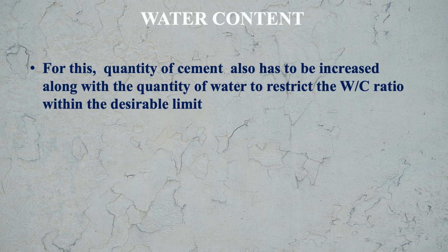Means if we have to at all increase the water content, then we can do one thing, that we can keep the water cement ratio constant, means within the certain limit. And how we can keep this water cement ratio within the limit? Means if you are increasing water, then increase the cement quantity also. For this, quantity of cement also has to be increased along with the quantity of water to restrict the water cement ratio within the desirable limit.